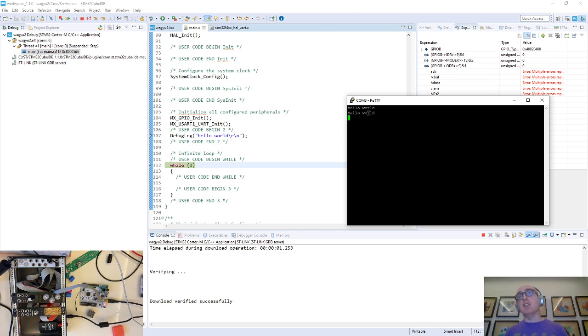So hooray, that is our little module down here talking over this thin grey wire to the ST-Link, which is then talking over USB to my computer, which is turning into a TTY in there. So basically, we now have debug TTY in. Next peripheral. And we basically just go through the peripherals and knock them down.